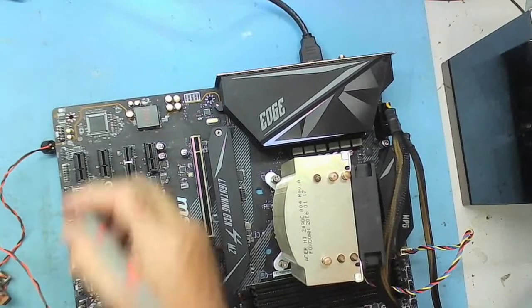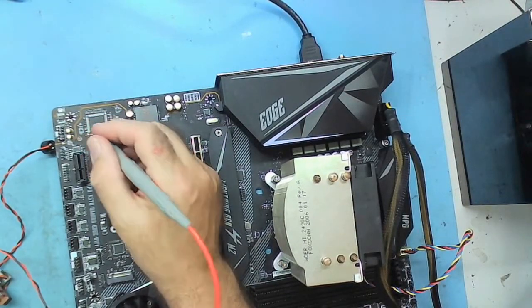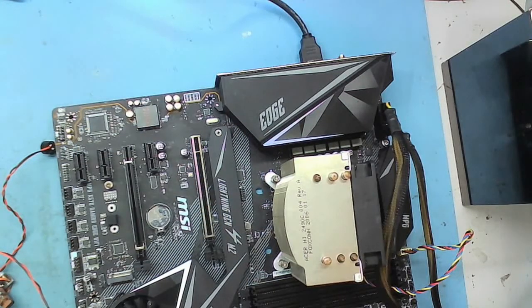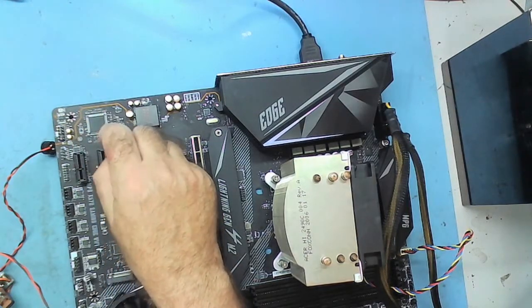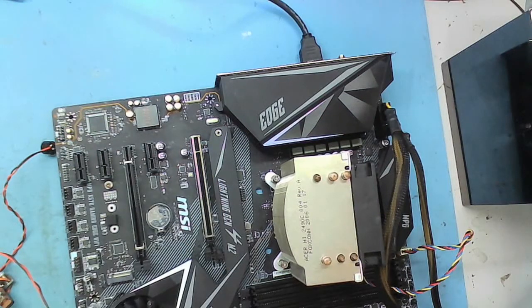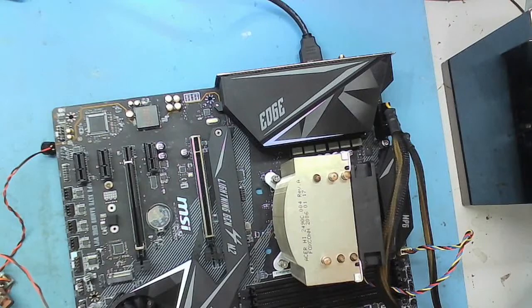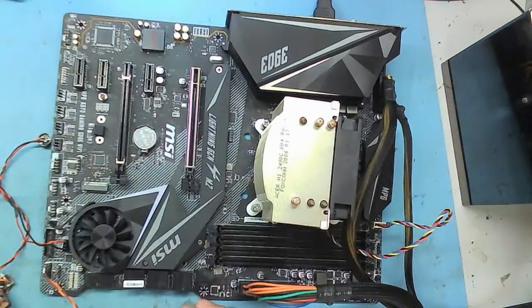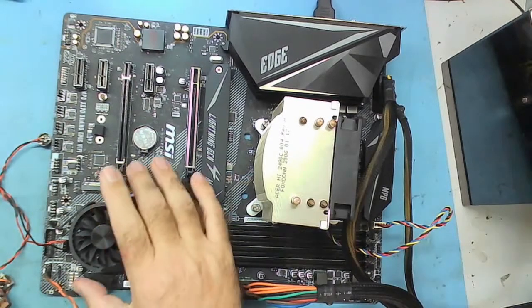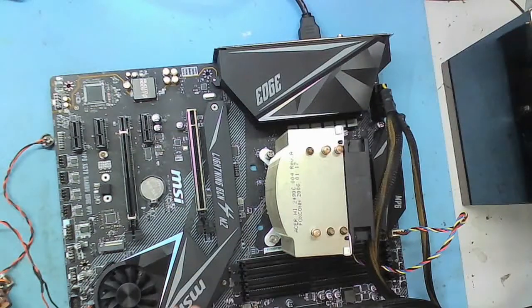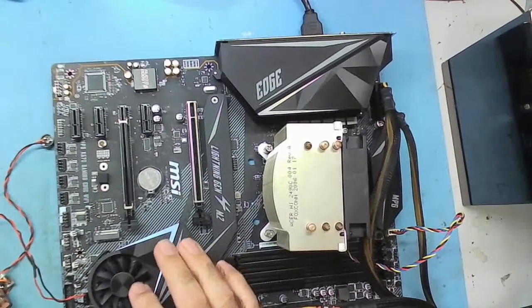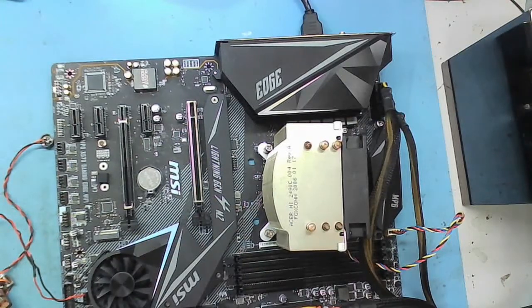So yeah, we could look up the data sheet for this chip. We could see what it is, and we could find out which of the little legs has got standby voltage on, and we might have to do that. But the easy way to be like 95% sure, probably more like 99% sure, is have a look around the capacitors in this area and see if you can find a 3.3 or a 5 volt standby coming in. There's almost certainly one on here, because I measured 3.3 on the switch, so there's almost certainly a voltage regulator here dropping that 5 down to 3.3. So I'm expecting to find 3.3 here, and some voltage, 3.3 or sometimes 1.8 on the north bridge. So there might be another voltage regulator involved. I wouldn't be surprised if it could be 3.3 standby, but I suspect it's likely to be less.